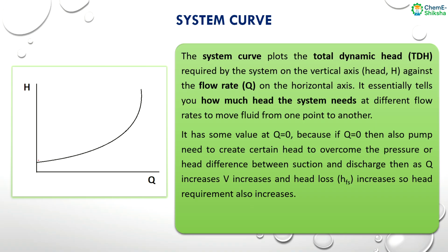Here also you can see that when Q is 0, at 0 discharge, H is not 0. We have some value of H at 0 discharge because at that point also the pump needs to overcome the pressure difference between the suction and discharge. So when Q is 0, there is no flow, but we still have a certain head, to overcome the pressure difference between suction and discharge.